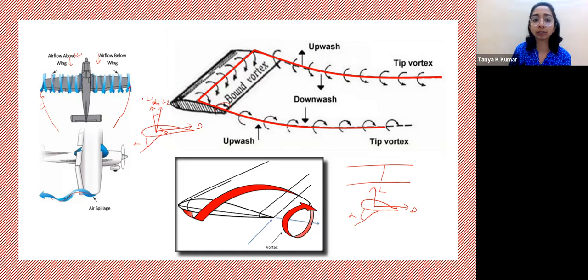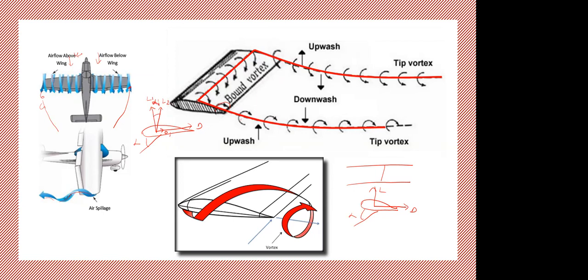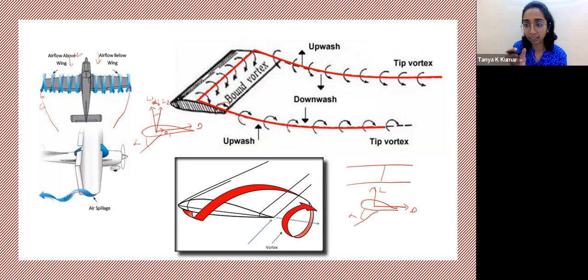Okay. So the lift is now tilted because of this new angle of attack at the tip. Because there is a change in angle of attack, correspondingly there will be a change in the drag. This change in drag, extra drag that is coming because of the extra angle of attack at the tip, is called induced drag, a small component.